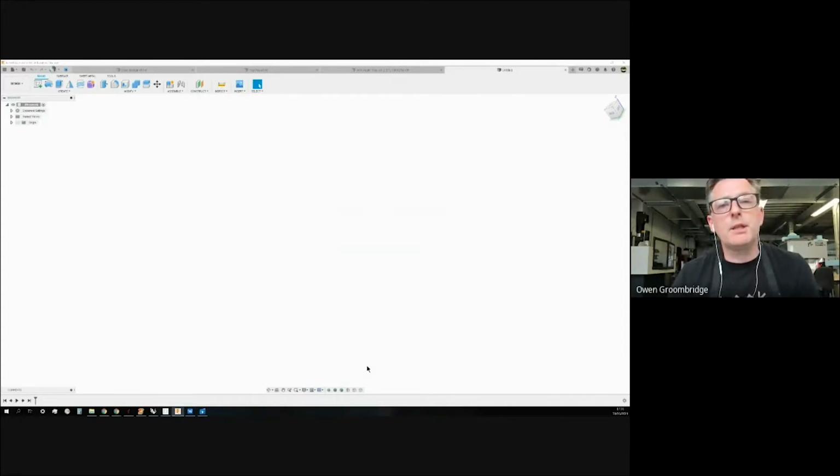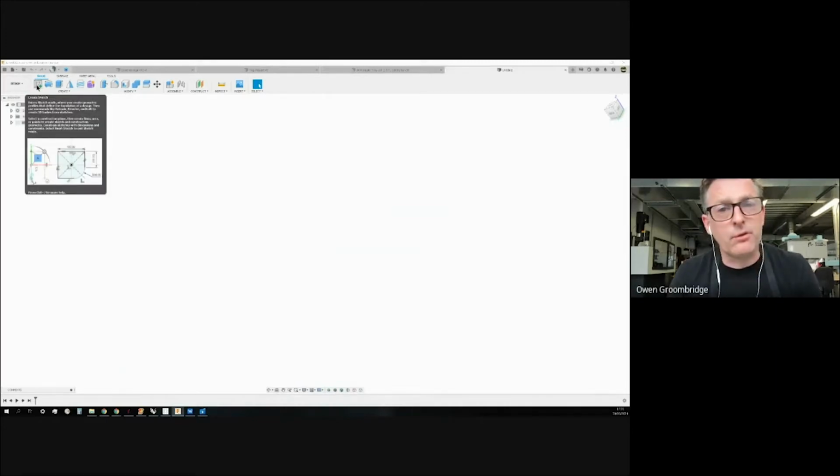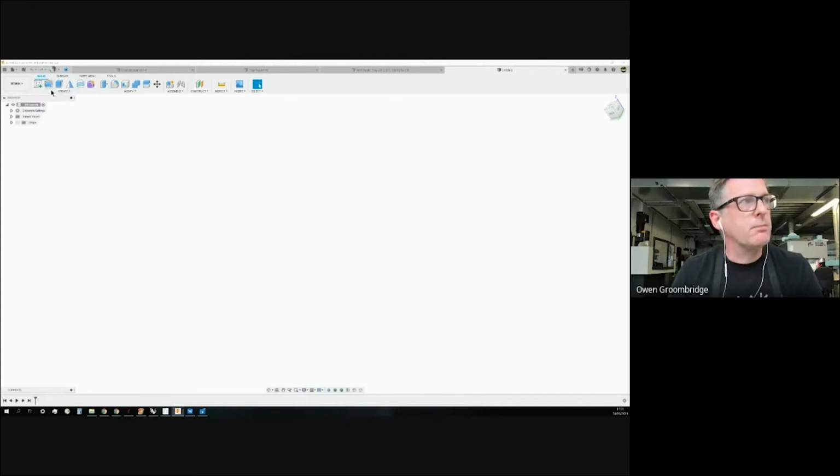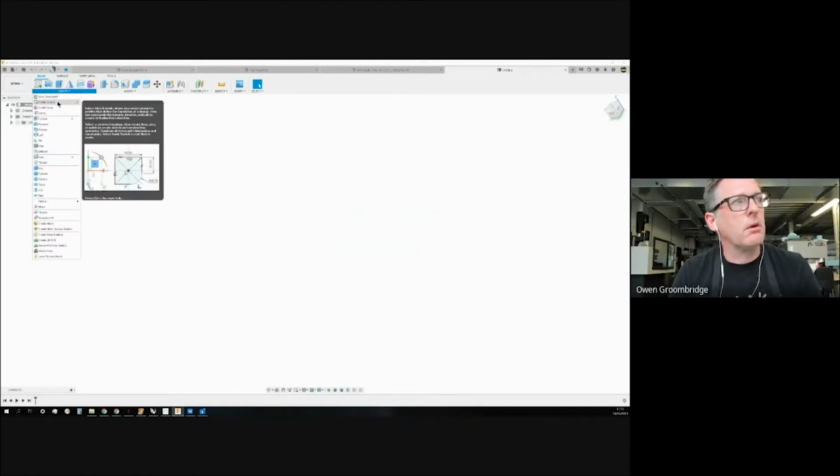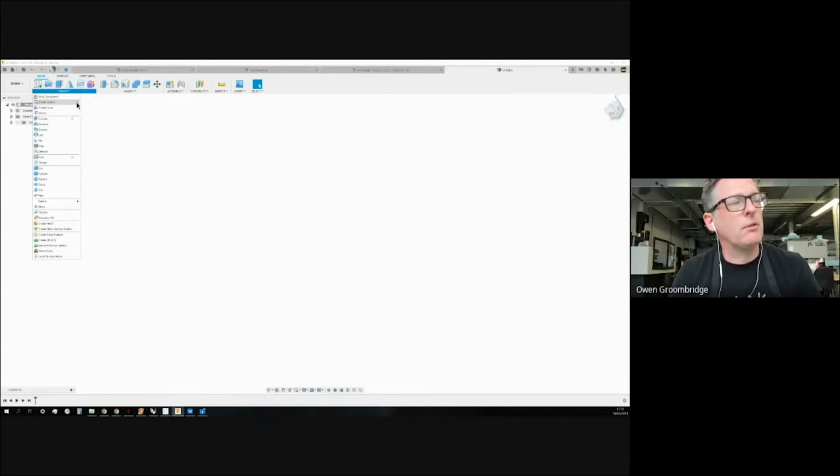So what you need to do is create a sketch in order for us to see this in action. So I'm going to go up to the Create Sketch button next to Design. If it happens not to be there for whatever reason, it's because under Create, it's been hidden. So you could go to Create and then Create Sketch there. There are 3 buttons, and if you left click on those, you can pin that to the toolbar or unpin it. So if it's not there, you can pin it to the toolbar that way, right?